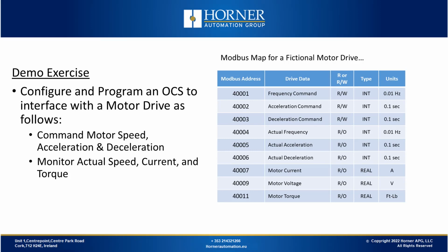One approach would be to have a different entry in our scan list for every variable and have several different reads and writes to grab this data. That, of course, is not very efficient as we have to send many messages over the network. However, since our data is all consecutive, another way we could do it is just to do a single entry in the scan list and read/write it all simultaneously in one message, which is much more efficient. So let's go about that approach instead.